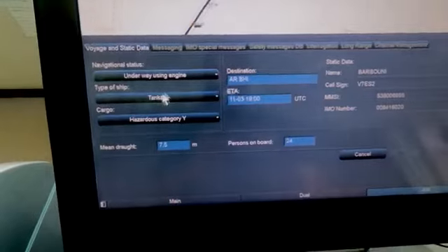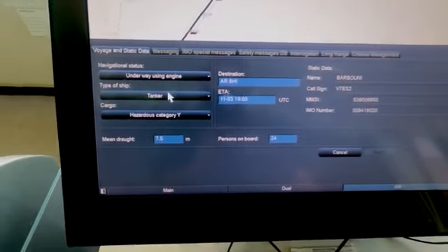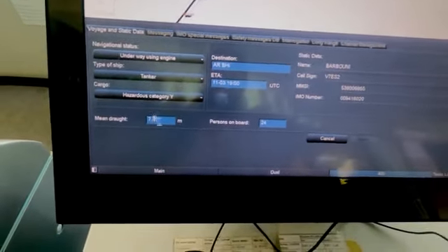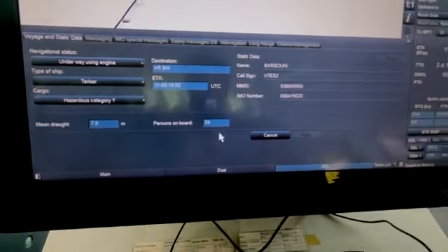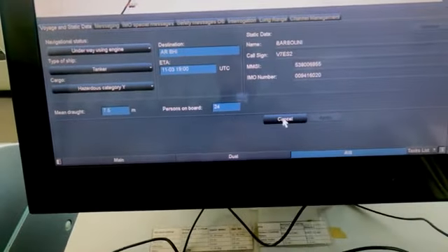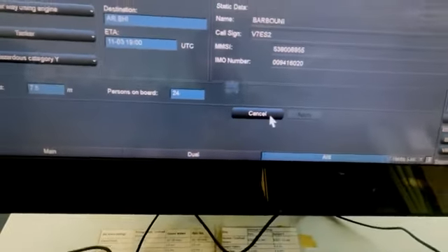So normally we use this voyage information which we edit normally for when anchorage, when berthing, for drafts, ETA, destination, and person on board. That's all. So after you put edit, you just have to click apply, and that's it. So that's the function for AIS.